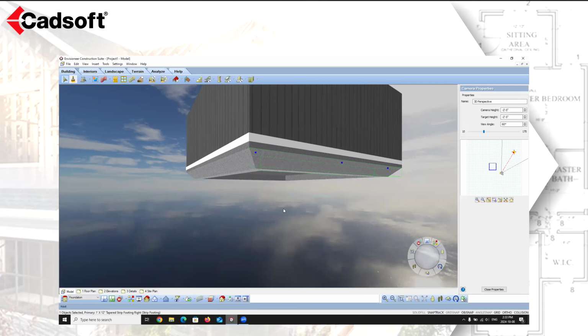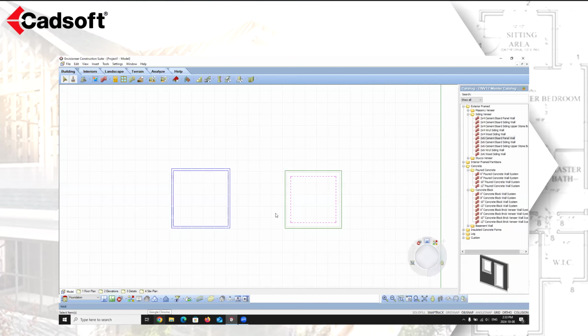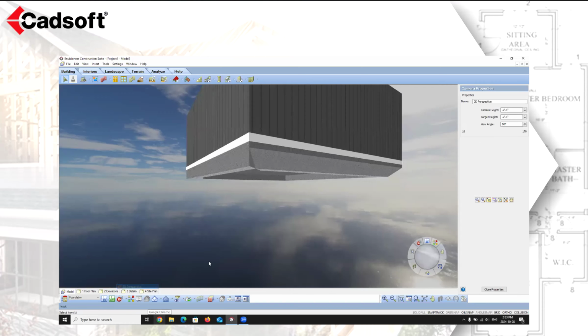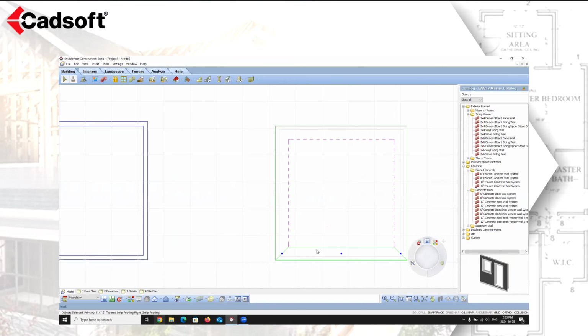Now the footings get inserted, and I don't know if there's a way to switch that on insertion, so I will probably have to just rotate it here. And let's see if that rotates it around. And then you can see there that the footing now gets rotated. And then we're just going to rotate all of these around. And then rotate.